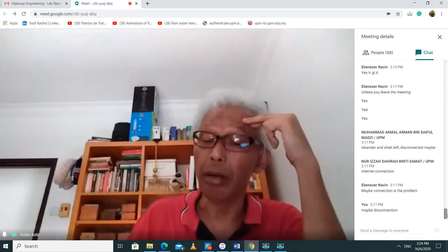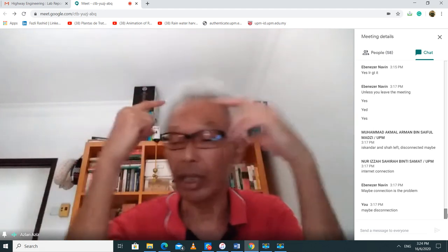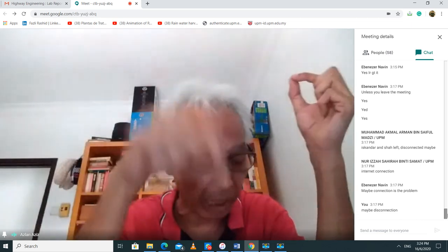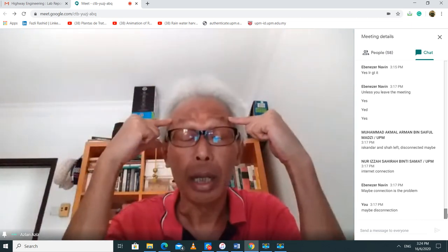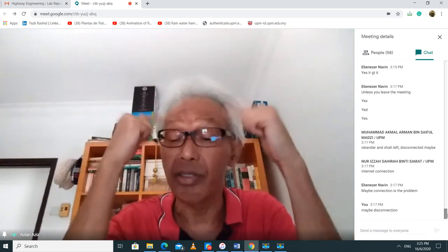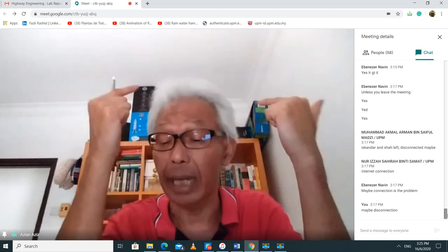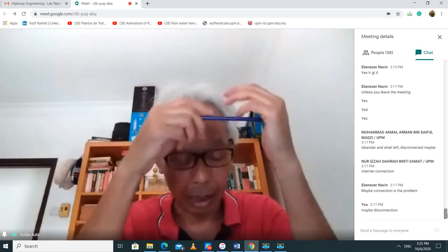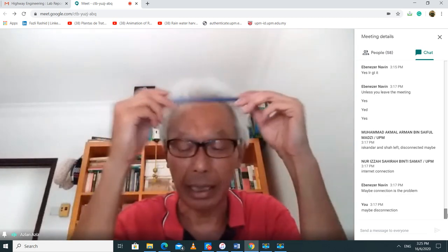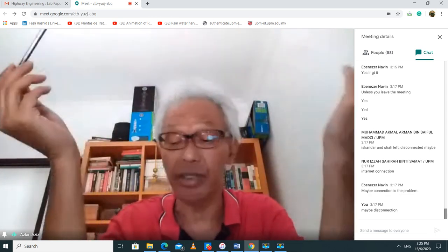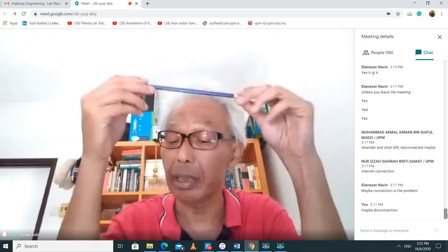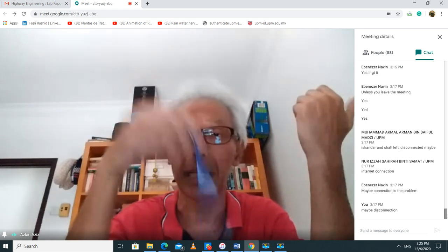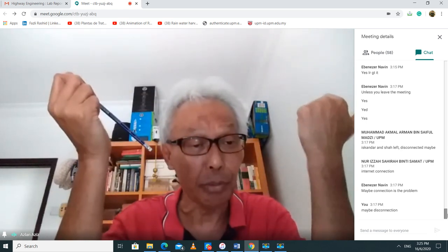All right, so I have M, which is the initial effective stress point. Again, for that initial stress point, you have to look at the picture which I drew on page 10 at the bottom. This is the initial state. And then I have N, the initial total stress point, which is the other picture which says later. And P is just the vertical stress increase following erection. The total stress path moves from N to P because now I'm applying the stresses from top to bottom to my element.